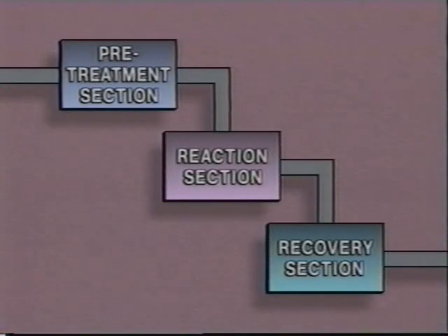We've just seen how input-output testing works as a troubleshooting technique for a single component in a process. You can apply a similar method on a larger scale through an approach we'll call bracketing. The goal of bracketing is to confine the problem to a certain process or part of a process. You establish the boundaries of the problem, and anything upstream or downstream of these boundaries is eliminated as a possible cause. Here's a simple example to illustrate this technique.